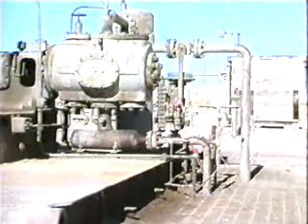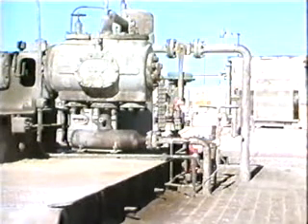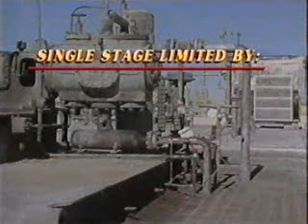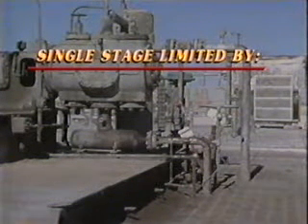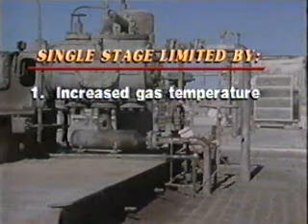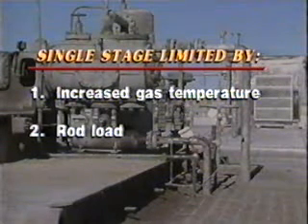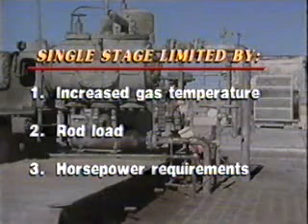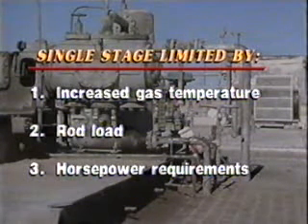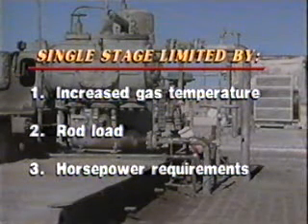Single-stage compressors can only increase gas pressure by a certain fixed amount. Factors that dictate how much a single-stage compressor can increase gas pressure include increased gas temperature, rod load, and horsepower requirements. So in order to obtain higher discharge pressures, there must be a multi-stage compressor package.